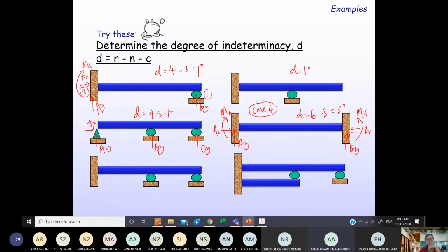I think at B. Okay, you can remove all the support reactions at B: BY, BX, MB. Therefore, you are going to have 3 redundant forces which you apply back later. The first may be BY, the second BX, the third MB. Imagine, because I do not draw it now, the determinate system will look like this, a cantilever beam, when you have removed all of BY, BX, MB.